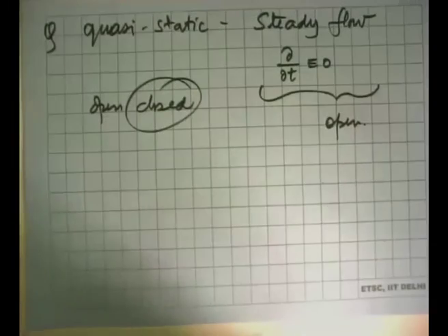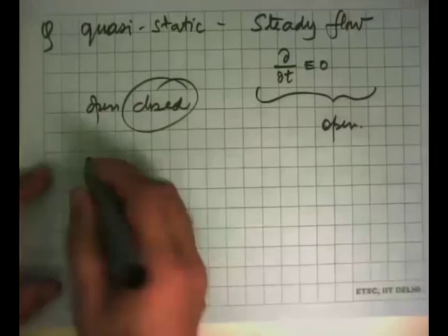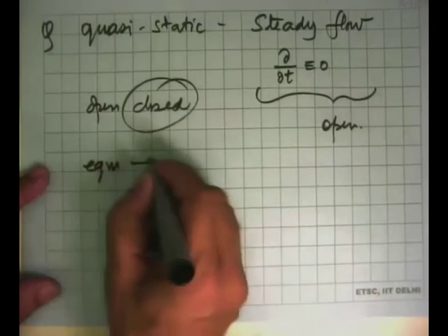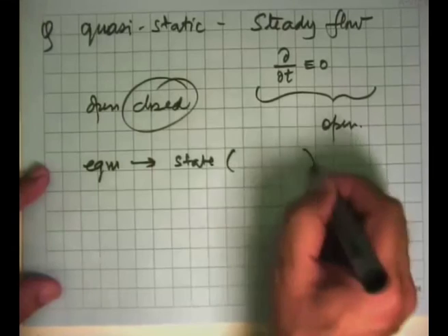So for instance, if the piston is moving, at any one particular instant I look at what is happening in the piston, and we say okay, it is quasi-static, or we can say quasi-equilibrium in that condition, and then we can assign properties to it. Remember that equilibrium is a necessary condition to talk about a state which is characterized by the properties.